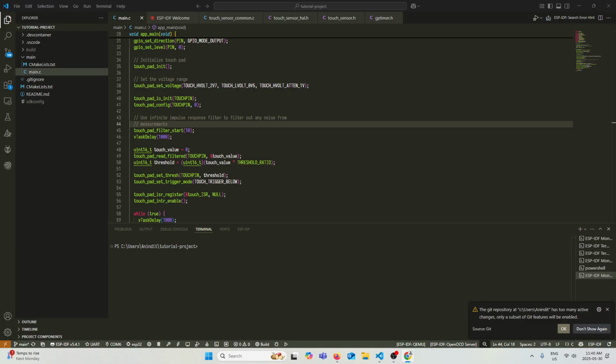ADCs can convert analog to digital signals in a variety of ways. In the first type of ADC, we can see how a comparator is responsible for each step change. Previously, we've learned that a comparator has 2 inputs. If the positive input is greater, the output is a high. I've definitely used these before in my lab. The analog input wave is converted to a 3-bit digital wave.